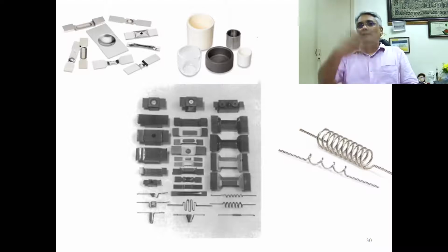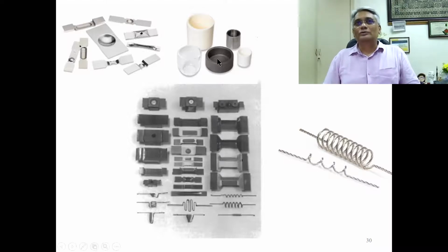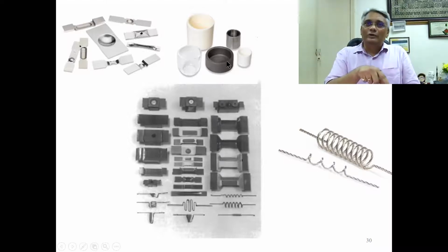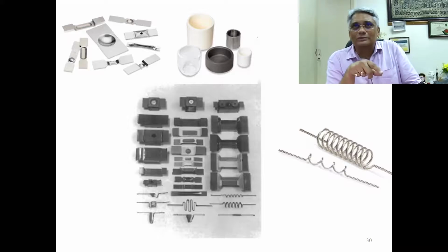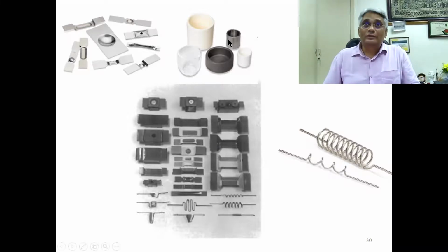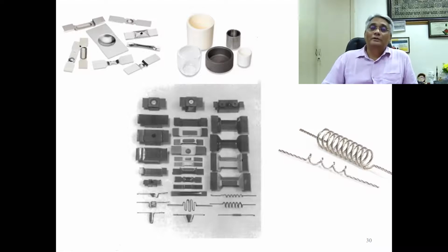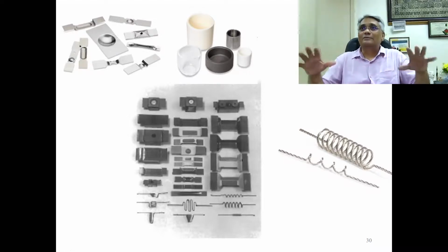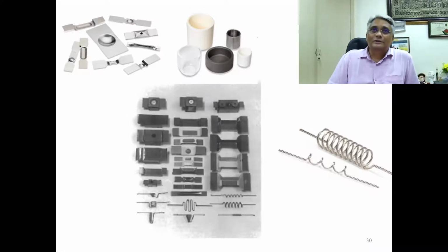That's it. The only way you can use the crucible is if you're depositing the same alloy composition, then in that case there's no contamination problem. You can't use it for any other alloy combination because then you're putting in the other elements that are already there. All right? Or you have to use a fresh one. So this is also an expensive process. But the process of the melt spreading out itself can cause contamination.